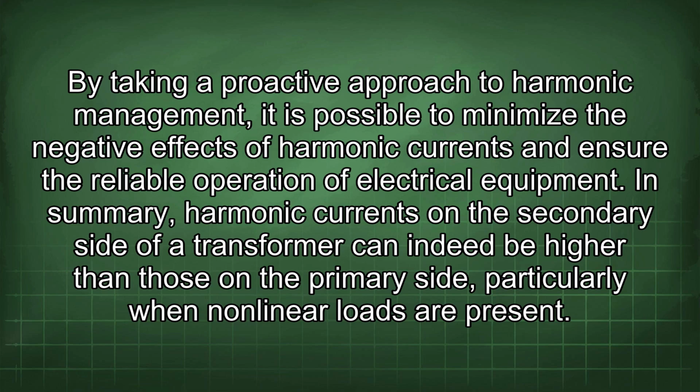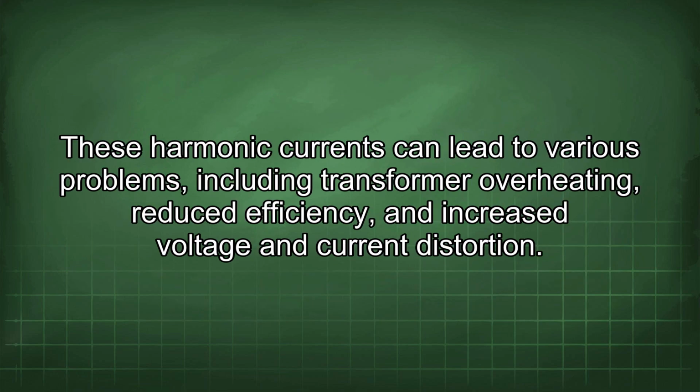In summary, harmonic currents on the secondary side of a transformer can indeed be higher than those on the primary side, particularly when nonlinear loads are present. These harmonic currents can lead to various problems, including transformer overheating, reduced efficiency, and increased voltage and current distortion.